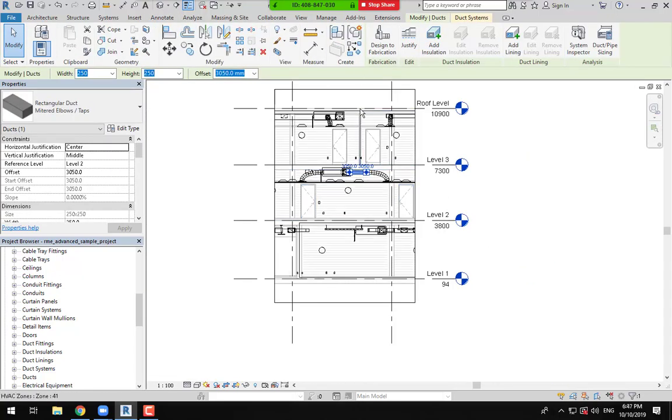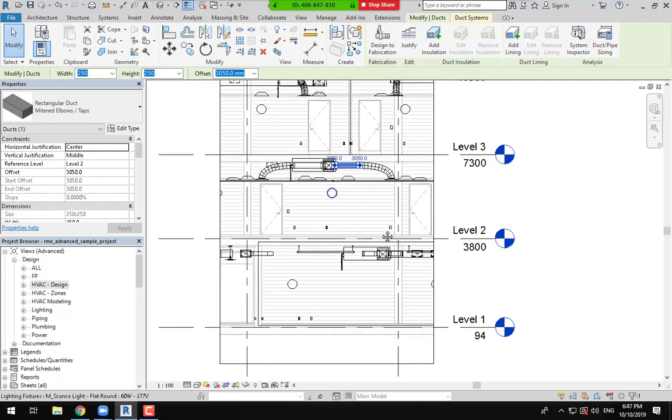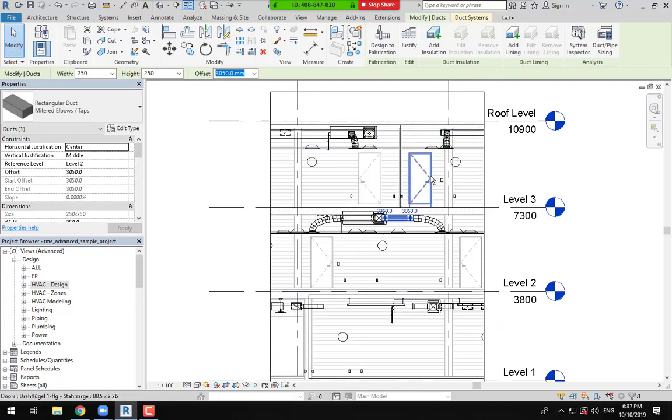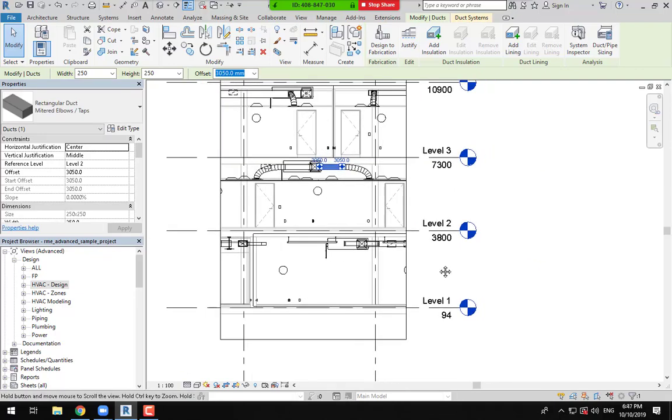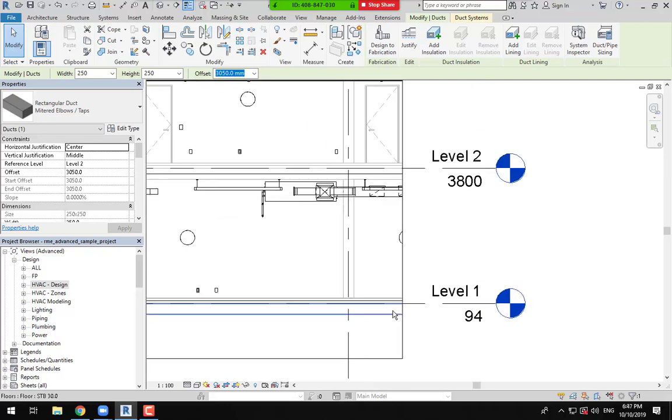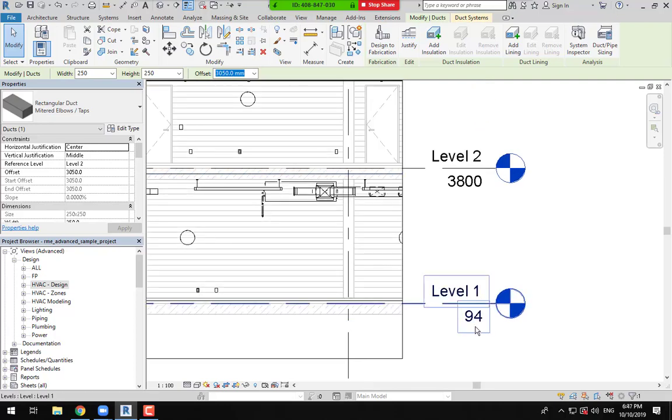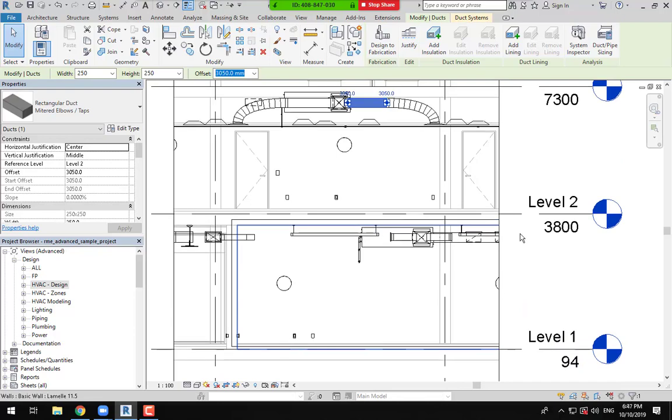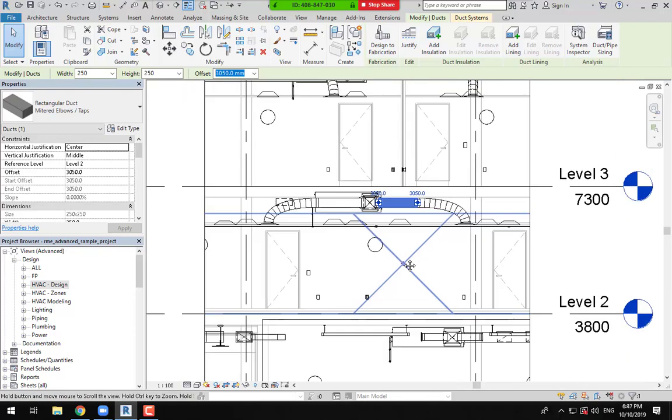The section, it takes a section in all your model. This is level 1 for your building. This is level 2. We are opening, or we were in level 2. This is level 2, and this is level 3. From where do I know this is level 1? From here. This is the beginning. The architect put this level here to define the level number from here, and level 2, and so on.